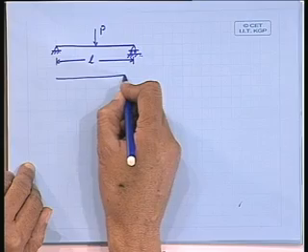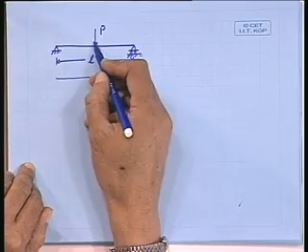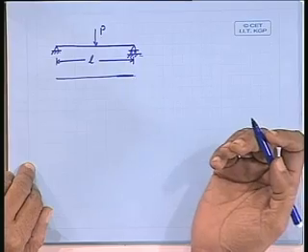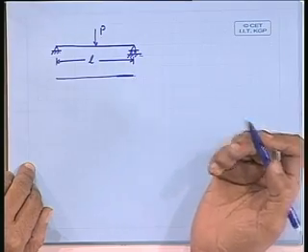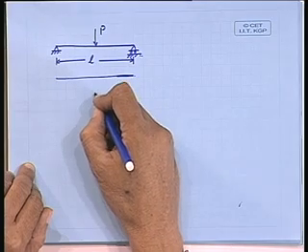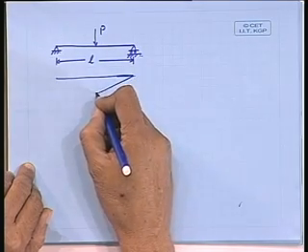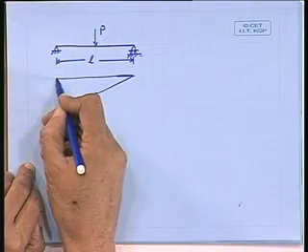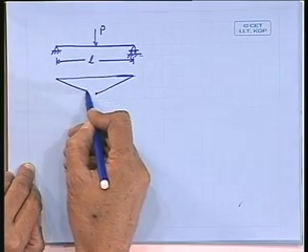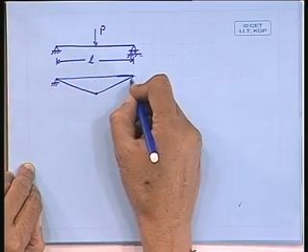Okay. So, this will have a mechanism which we have seen, that under this load the maximum bending moment will occur, and the bending moment diagram we know will be a triangle. So, let us assume that the first hinge is formed here, and the first plastic hinge is going to lead to the failure here.